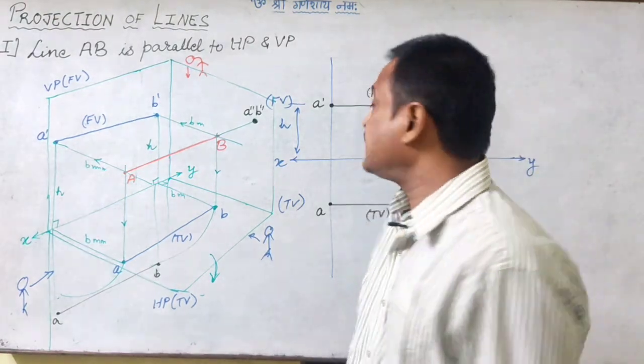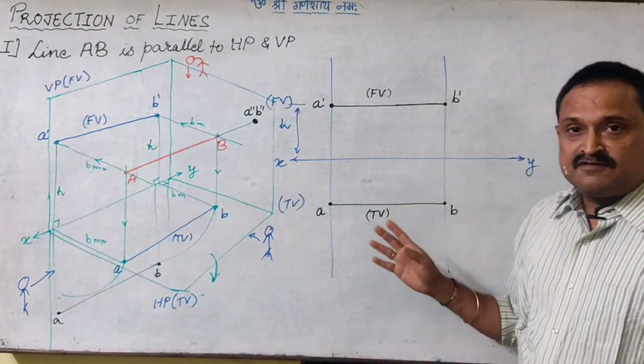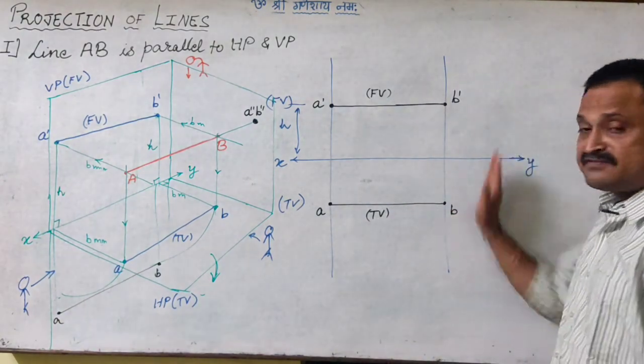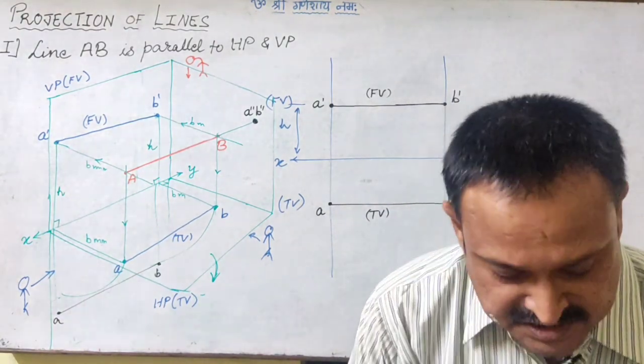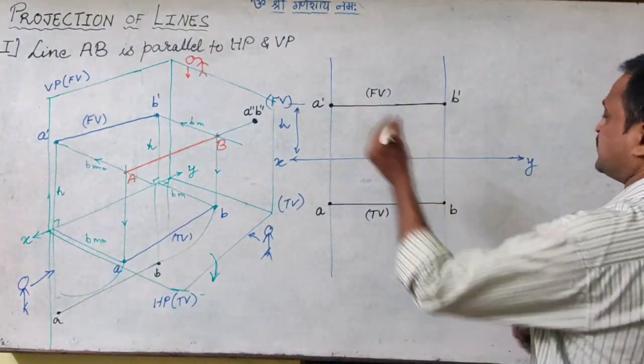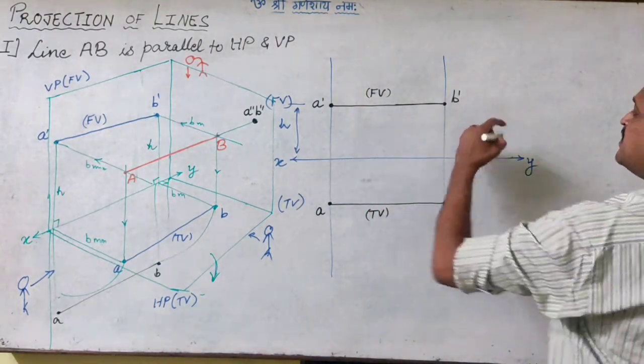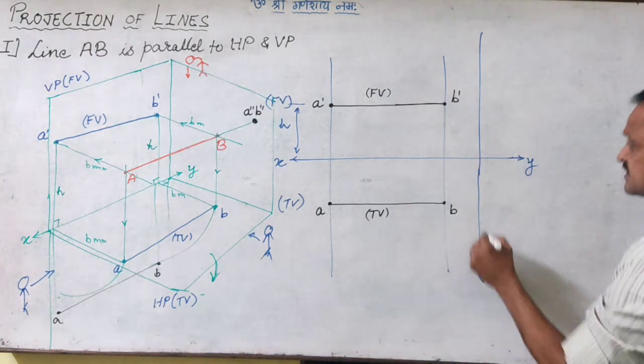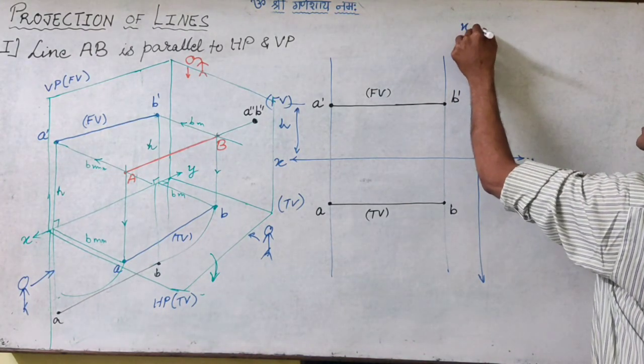So let us check that with the fundamentals of the first angle method of projection, whether we really get this as a point or not. From the front view image, at a comfortable distance, we will consider the second reference line as X1Y1.